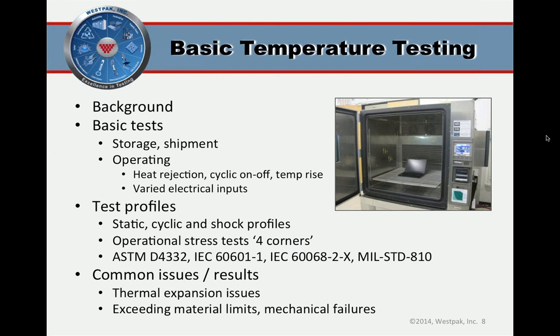Another common thing we'll do is to vary the electrical input into the product. So imagine this thing has a universal power supply. It can take, say, 100 volts AC to 240 volts AC. How does it operate at those extreme conditions at varying temperatures?